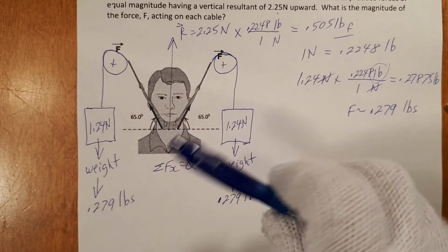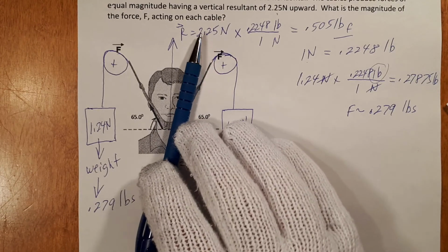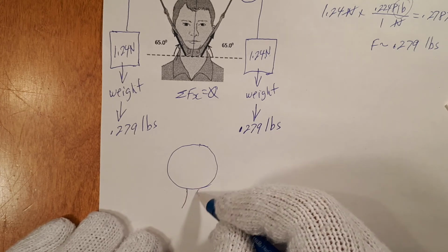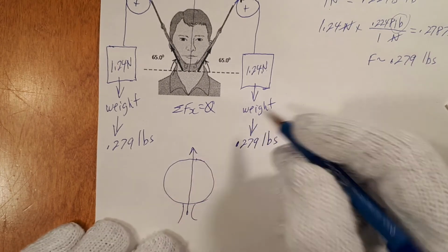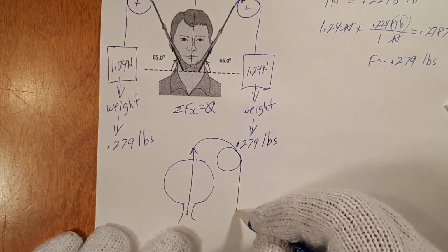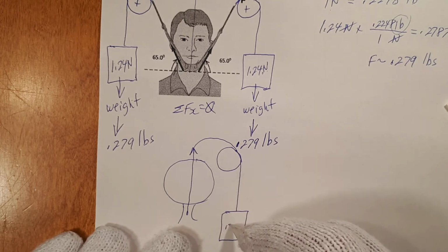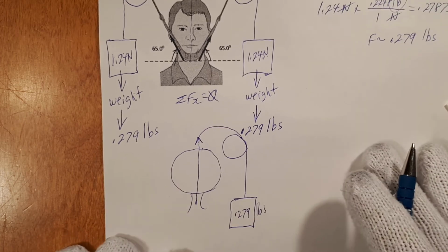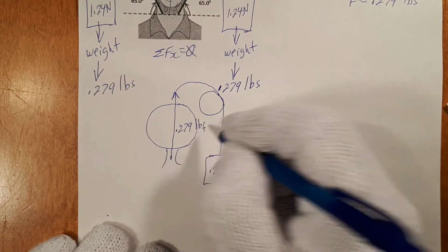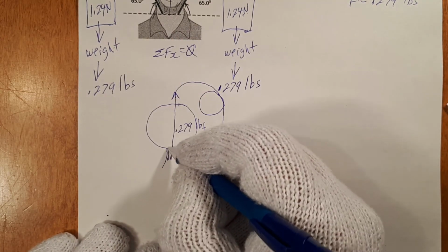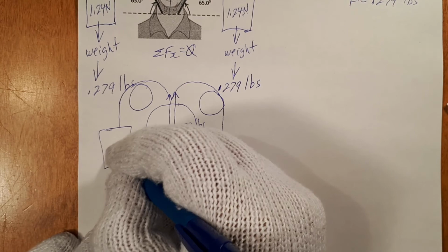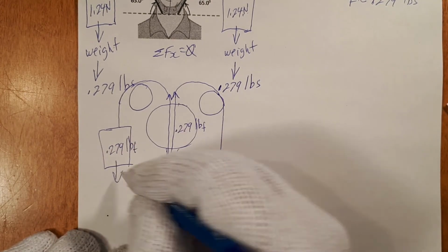So I'm going to redraw this, and I'm going to take that quarter of a pound, or 0.279 pounds, and put it straight on the head, pushing upwards. If I were to redraw this, here's the gentleman's head. He has his neck. And I'm going to place the whole weight completely upward, and the rope is going to come around the pulley. Pulley doesn't really change anything other than the direction. And I put that 0.279 pounds coming down here. So that full 0.279 pounds is now being applied to the head upward. And I do it again for the other side. And there's a pulley, and it comes down, so I have that weight here. So both weights are pulling down.